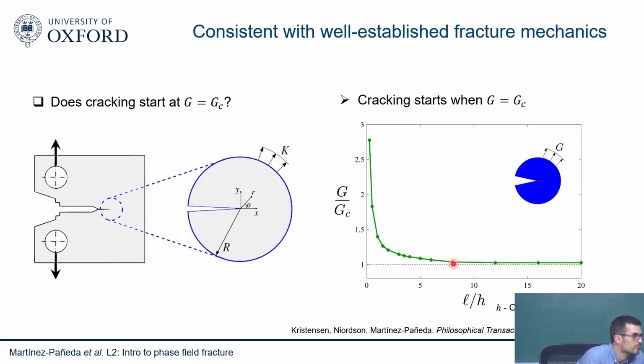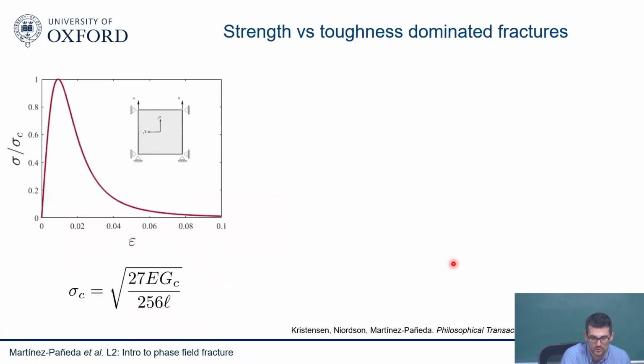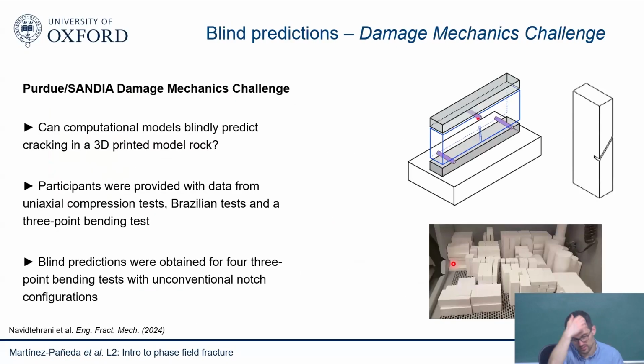Suppose we consider the same plate in 3 dimensions, and we know it is uniform in the thickness direction. So in thickness, we can have a smaller number of elements compared to where the crack is propagating. Well, if you have the crack propagating through the thickness, you need to resolve that. I'm going to show an example right now in 3D, so you'll see it. But you do need to resolve that. Yeah. Okay, so this is the example that we're going to show.